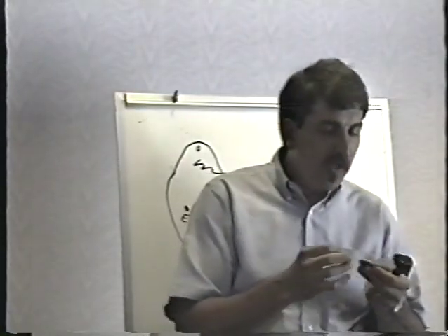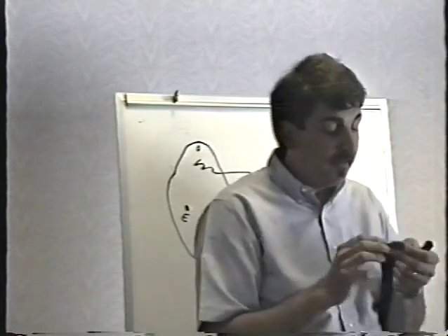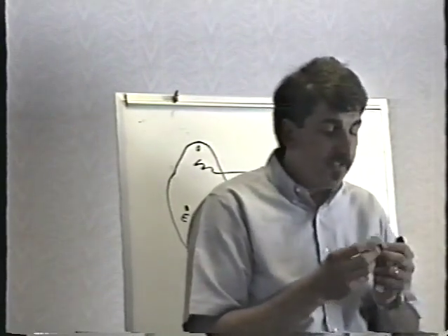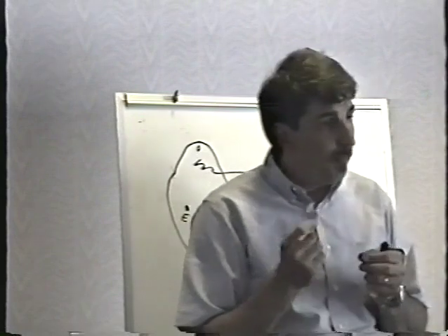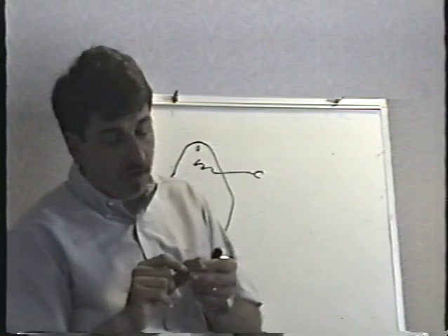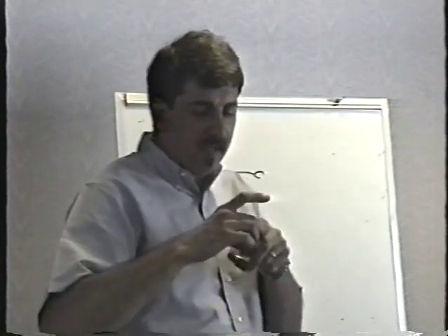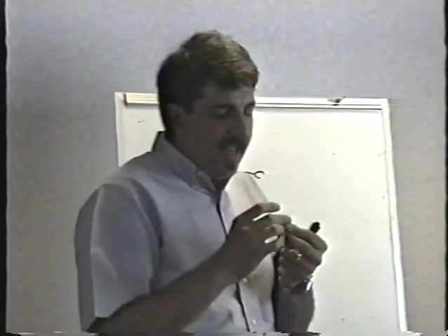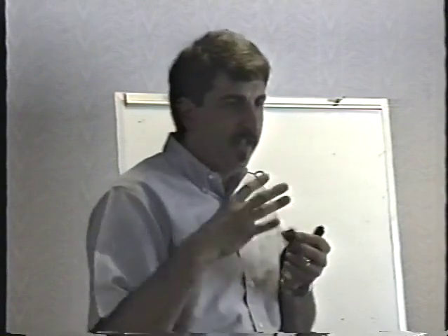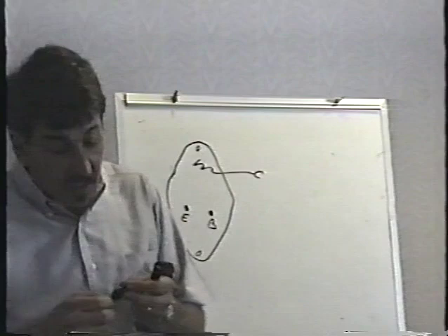So this white goop did not come out of the transistor, although the transistor is filled with the same stuff. It's called heat sink compound. You'll probably see it on Wednesday when we pull the power supplies apart. It's put on the back of the transistor and also on the insulator and on the heat sink, to help conduct heat away from the transistor. It's not electrically conductive, just thermally conductive.